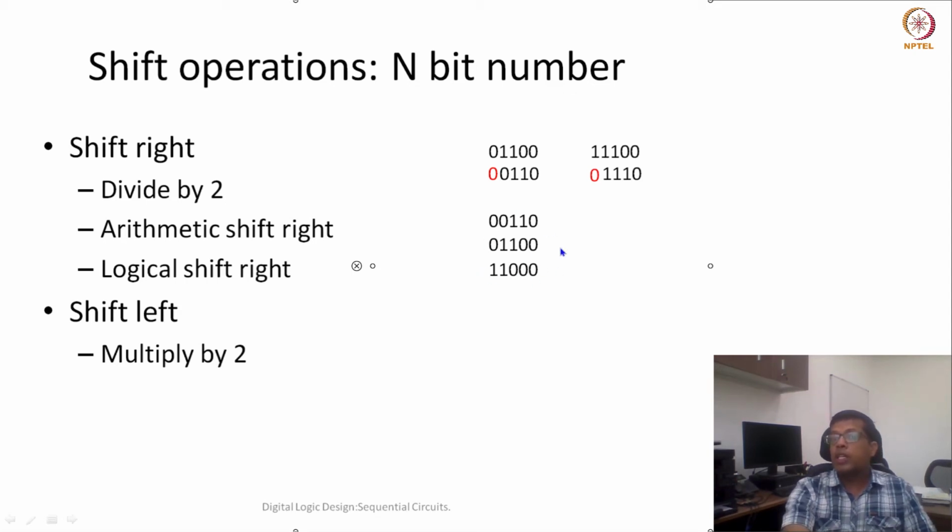So in a 5-bit number, the range of numbers could only be from 15 to minus 16, because 12 times 2, which is 24, is outside the range. This has become an overflow. So overflow is an error. Although this number could be a negative number, if we are trying to put it as a positive number in sign notation, then this becomes an overflow.